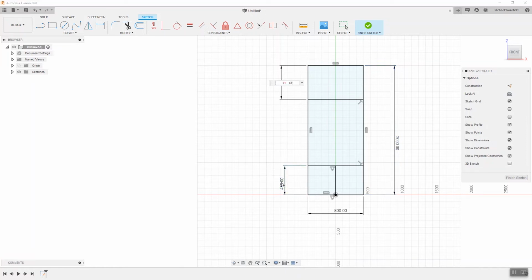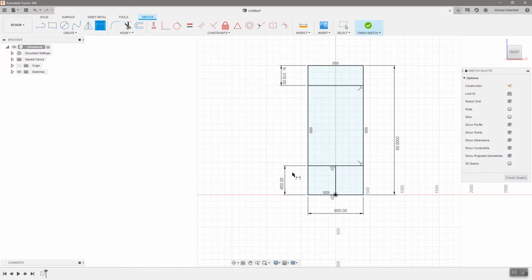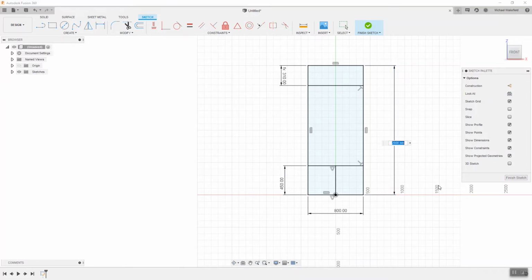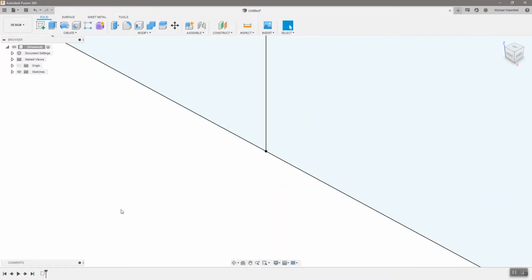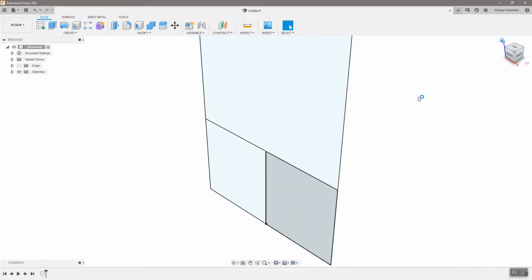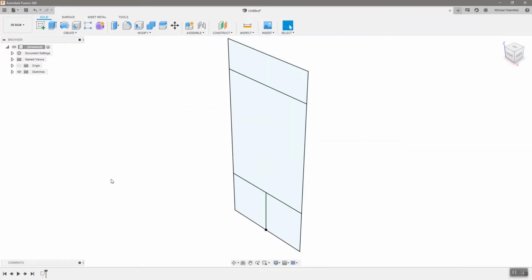You'll also notice I'm using the parametric functions of Fusion to create a relationship between that top shelf, its location, and it is going to be of the correct size so that I will always have 5 shelves equally spaced in that top section of my assembly. After that sketch is finished, it's very simple, but I can begin using that sketch to create other entities.